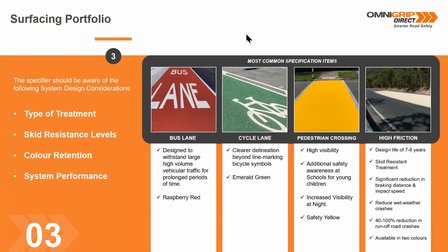So we've covered some skid resistance elements in reasonable detail in the previous slides, but it's namely about the requirement as to whether this is for vehicle traffic, in which case you need a particular aggregate size, or if it's non-vehicle, in which case that would be suitable for pedestrians. And it's a very important component when considering application for surface treatment. Step 3 is the colour retention.